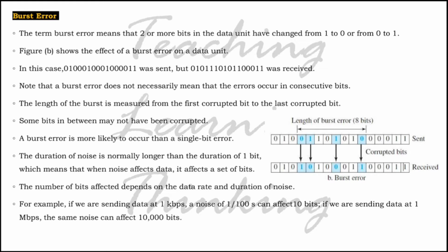So we cannot say that the errors must occur in consecutive bits. The length of the burst is measured from the first corrupted bit to the last corrupted bit. So some bits in between may not have been corrupted.